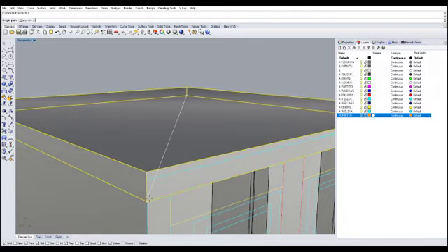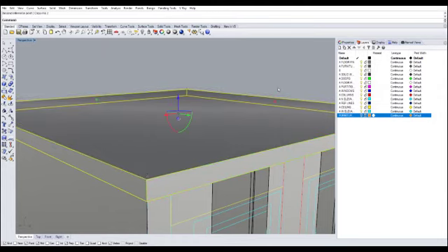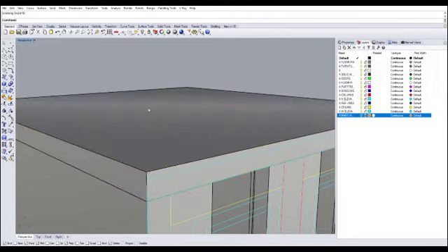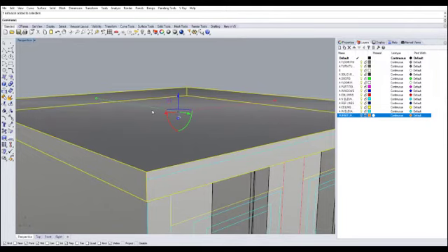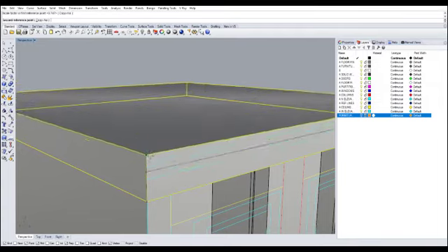So let's click the point of origin. Oh, sorry, wrong. Click the point of origin, and then let's click on that guy to bring it down there. So once again, let's try it one more time. Select the object, type Scale 1D, point of origin is here, and then we want to bring that guy down here. So click the point of origin. Next it's asking for the first reference point, which is this guy. And then of course it allows you to bring it up and down.